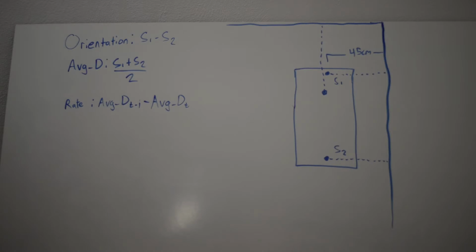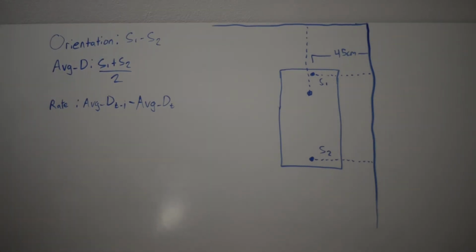In order to create a reliable, non-oscillating wall-following algorithm, many new data points had to be taken into account. Given the two sensors on the right side of the rover, we can determine the following: the orientation of the rover with respect to the wall, the distance of the rover from the wall, and the rate at which it is moving towards or away from the wall. The third data point is determined by keeping the distance of the rover from the wall at the previous iteration of the algorithm and subtracting the current distance from it.